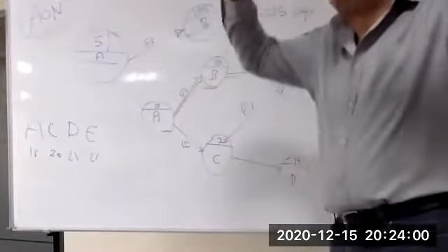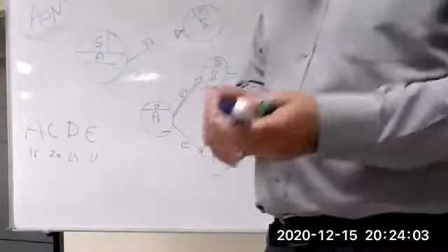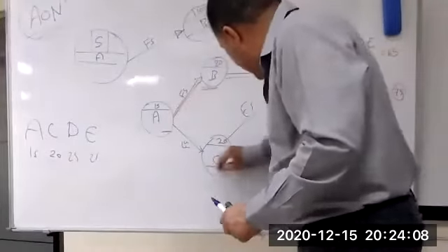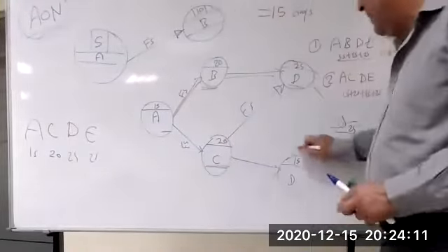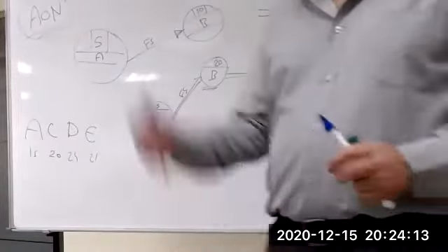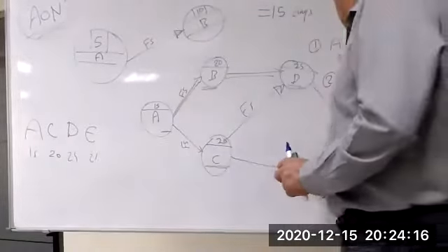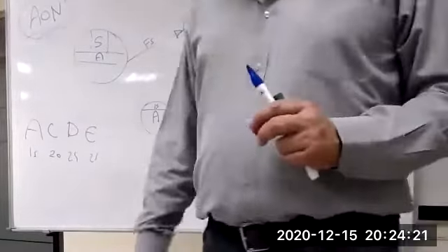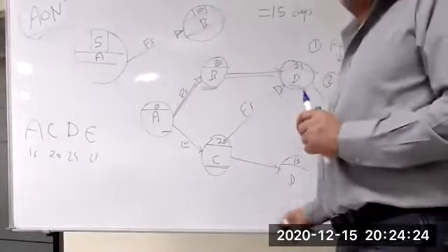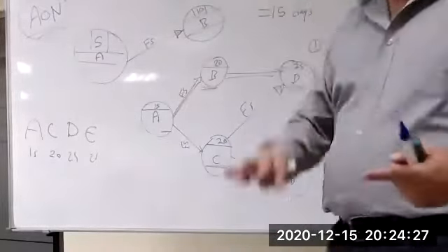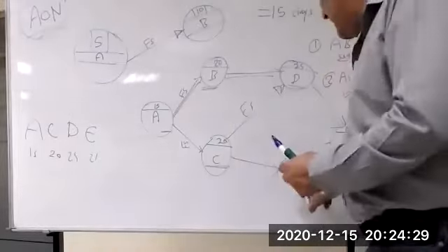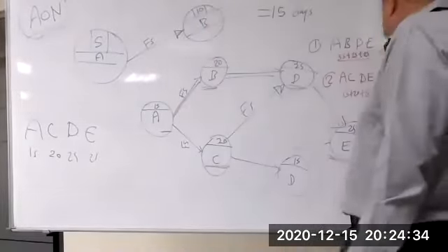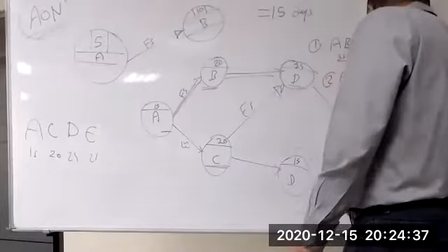Now we have two critical paths. Simple. This activity as well is critical now. Only one activity is not on a critical path. How many days of float does this activity have? 10 days, in your example. What is the total float, or slack? Slack float, okay? For the activity, now it is 85, and that means 75. 85 minus 75 is 10.